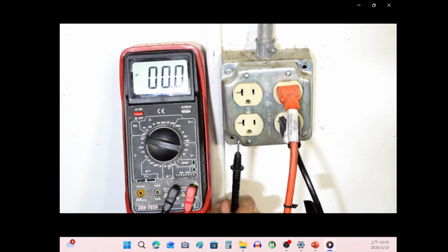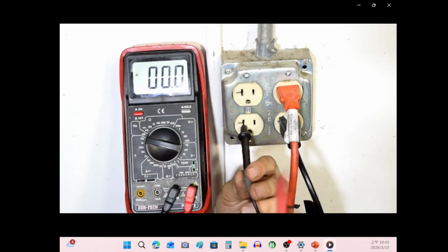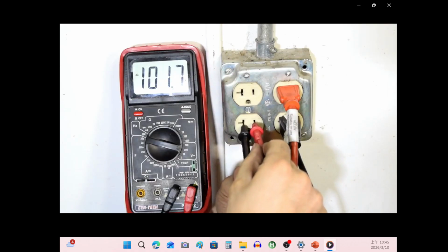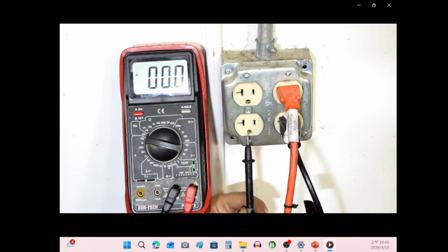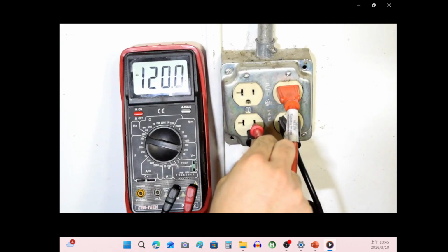So next we grab our ground test lead and we're going to put this in the bigger slot on our wall socket. And then we grab our red test lead and we're going to put it on this other side, which is the power side. And as you can see, we got 118 volts coming out of this, which is about right. Also, if you ever wondered what this one is for, this is your case ground. And a good way to check it is to see whether you get a reading when you do this, and we do, so this is good as well.